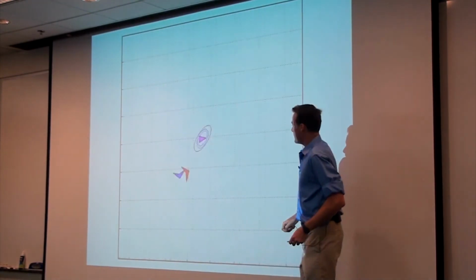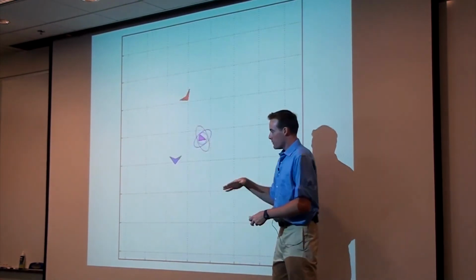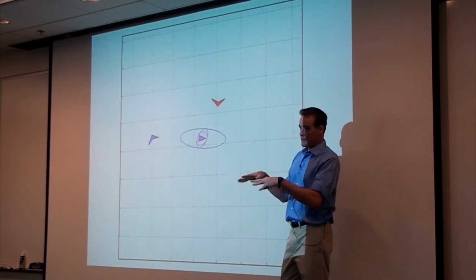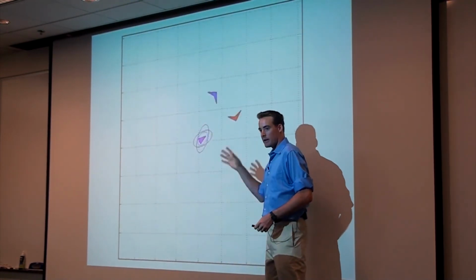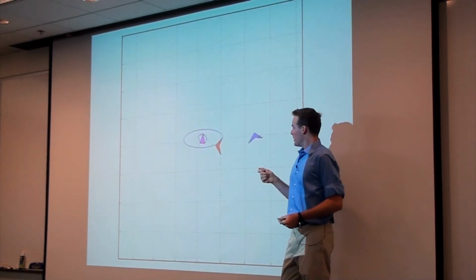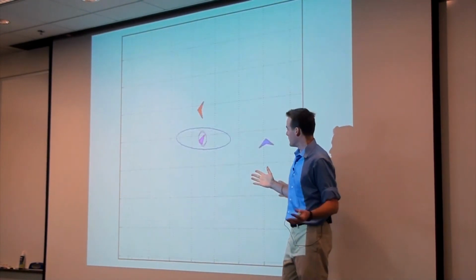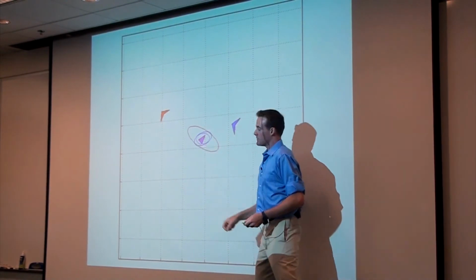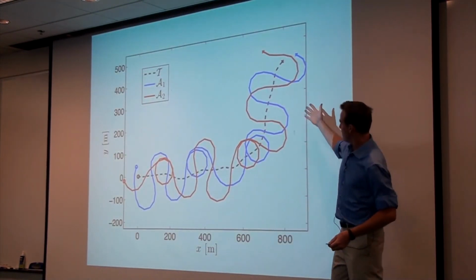So here's an example of his algorithm running. The truck is sort of randomly moving and driving and so on, and the UAVs, you can see, are not staying at 90 degrees at all. It sort of looks more like they're taking turns swooping over the target. Now, Stephen did not explicitly say in his code, please swoop over the target, alternate and swoop over the target. That was just the result of his optimization, which aims to minimize the size of the combined uncertainty ellipse. So what this looks like in the whole, this is the whole flight.